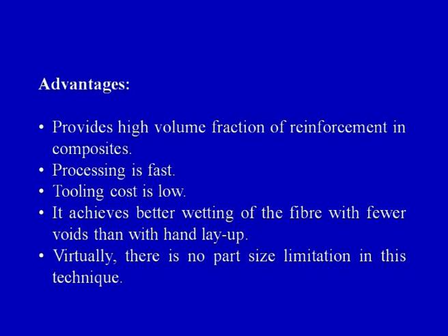Now what are the advantages of the spray layup process? Spray layup provides a high volume fraction of reinforcement in the composite. In the previous lectures we saw what we mean by volume fraction. Volume fraction means the amount of fiber which is reinforcing the matrix phase. So we may have 60-40, 40-60, 50-50, even 30-70: 30% of fibers and 70% of the matrix, 20% of the fibers and 80% of the matrix, or 10% of the fibers and 90% of the polymer or the matrix.